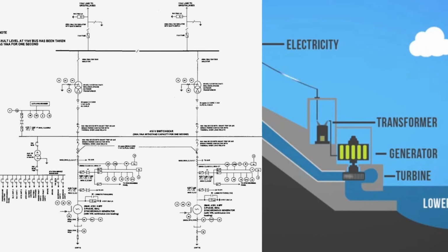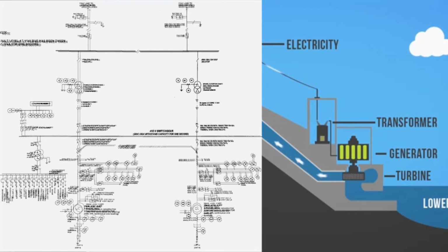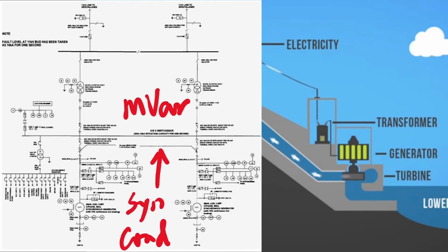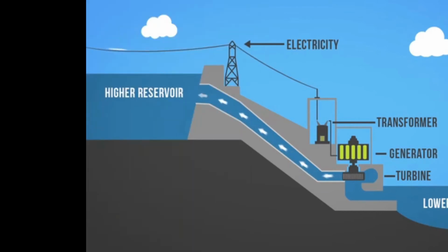The advantages of hydropower plants are: it is clean energy with low production cost. The resource is adaptable to changing demand. It can be used as a base or peaking power, and a quick start within 1 minute. Also, it can be designed as a synchronous condenser to provide MVARs, relatively simple operation and maintenance, and a high efficiency, usually at 80 to 85%.